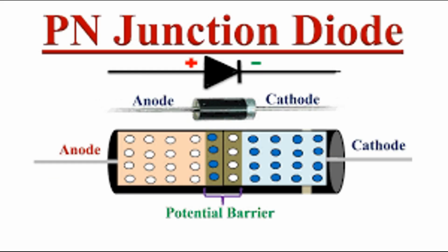Applications: voltage clipping is used in audio and music effects circuits, distortion pedals, and guitar amplifiers to create distortion and overdrive effects. It can also be used in video signal processing and communication systems to shape or limit signal amplitudes for specific purposes. The specific threshold voltage of the diodes and their arrangement in the circuit determine the characteristics of the clipping effect. By carefully selecting diode characteristics and circuit parameters, engineers and audio enthusiasts can achieve desired levels of distortion and signal shaping, leading to unique sound effects in audio applications.